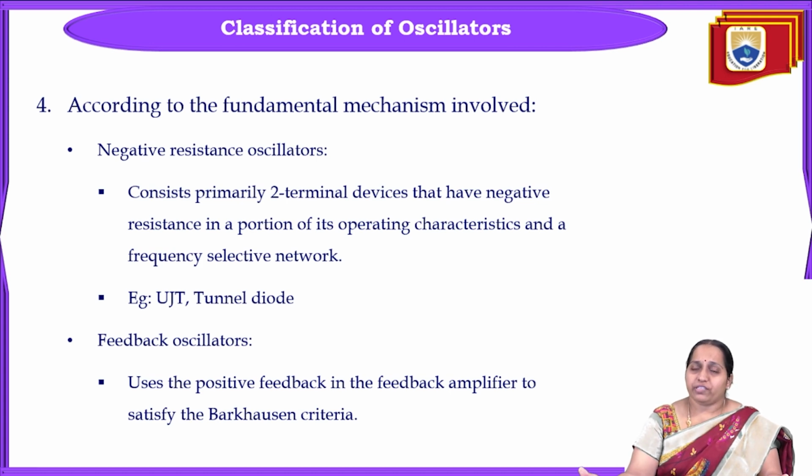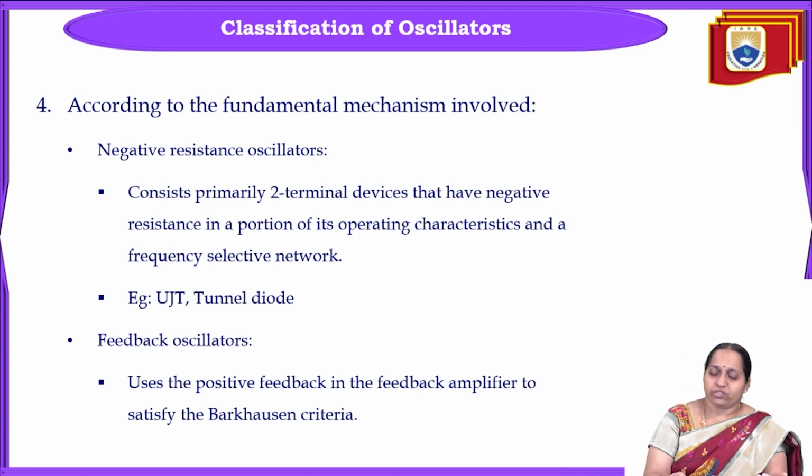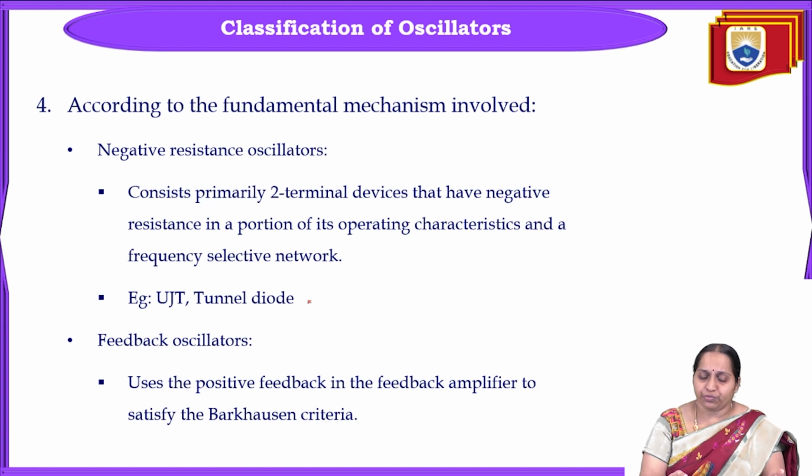That is, after reaching a certain voltage, if you increase the voltage further, the current will reduce. That is what is called the negative resistance effect. So using these negative resistance devices, when they are operated in the negative resistance region, these are called negative resistance oscillators.